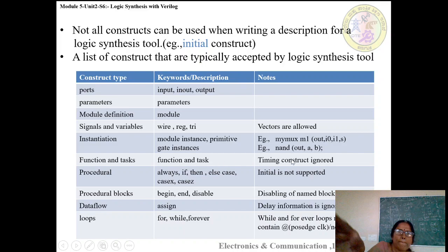Here, timing constructs are ignored. And for procedural constructs: always, if, then, else, case, casex, casez. These are the keywords we are using, and initial is not supported.